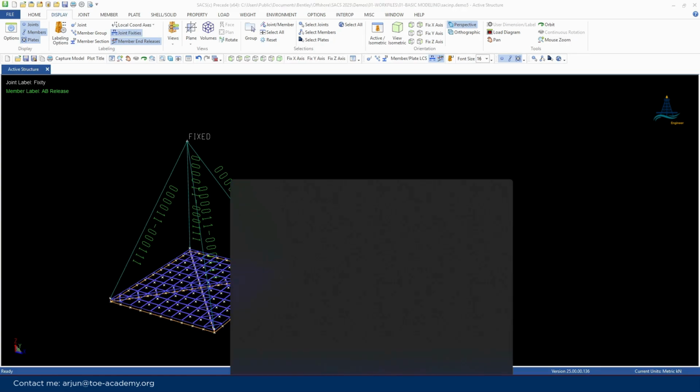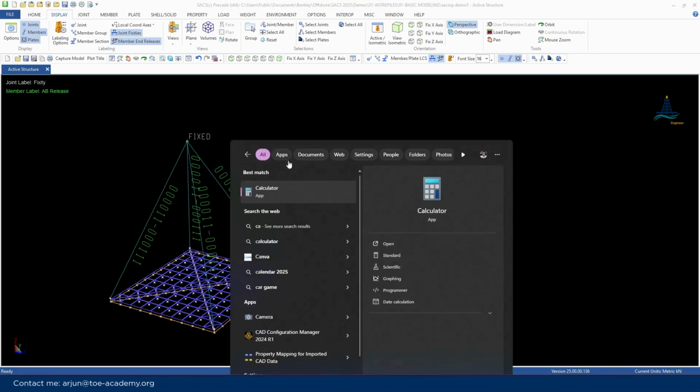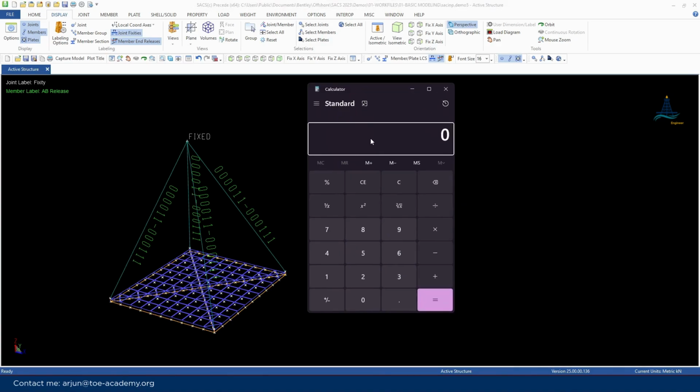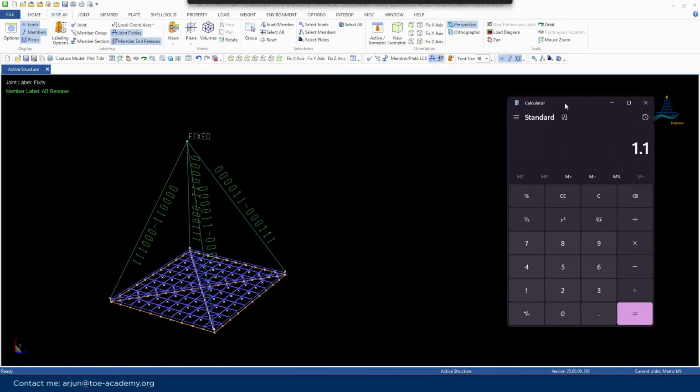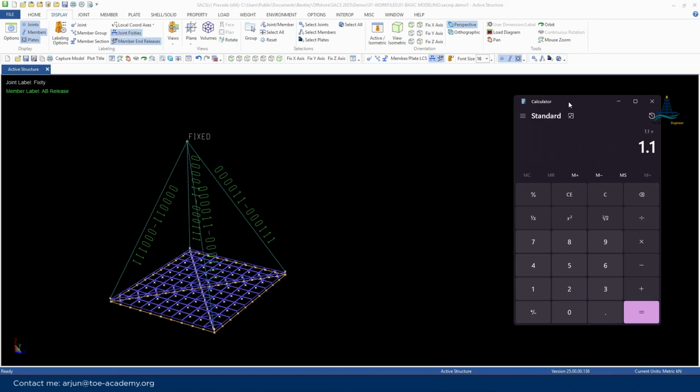So let's say we have a few factors. One is the weight contingency factor of 1.1. The next one is the DAF factor. I am going for a subsea lift, and if the load goes down, the DAF will come to 2. Then the consequence factor of 1.3, the COG shift factor of 1.05, and this Q factor of 1.5.